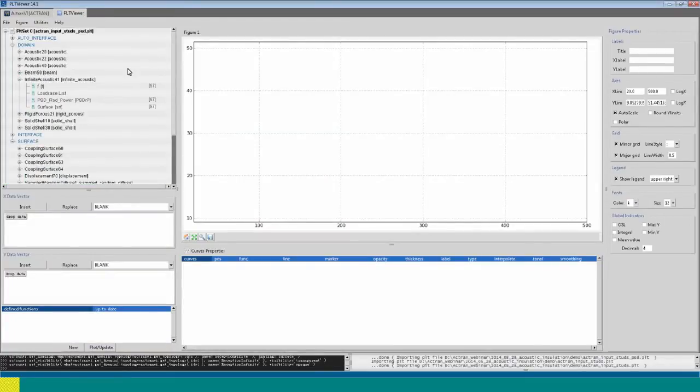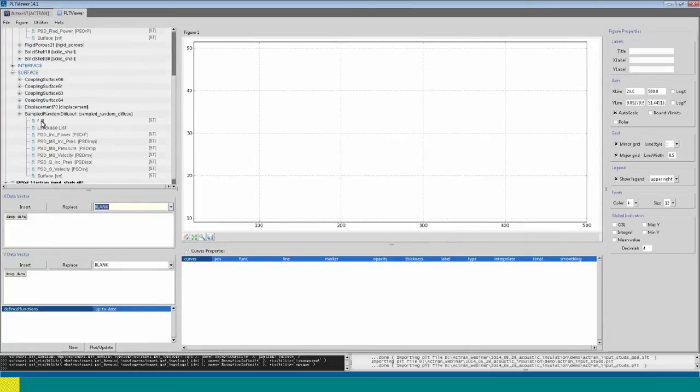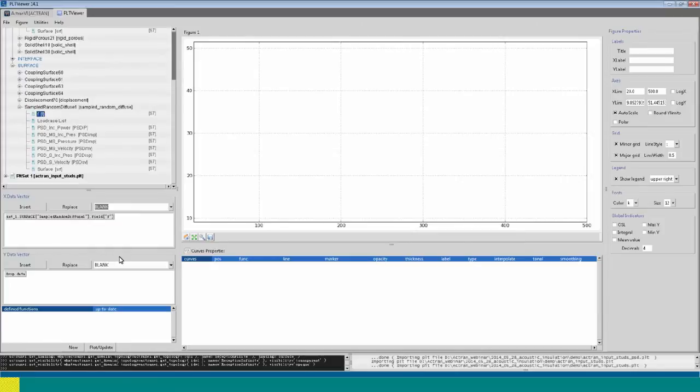The result we will look at is the sound transmission loss indicator, and it can be plotted from the text result in this PLT format by Actran. So basically, we will need a ratio between the incident power and the transmitted power. And to do that, first on the x-axis, I will apply the frequency. Okay. And on the y-axis, I will apply our transmission loss indicator.